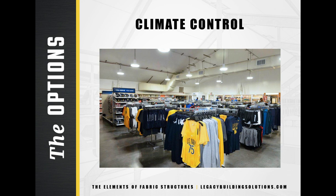Fabric can also make the interior of the building more comfortable, as fabric has thermally non-conductive properties. Unlike steel, fabric does not magnify the outside temperatures, maintaining a more consistent interior temperature. Metal cladding will radiate the temperature variation, creating an interior that is colder in the winter and hotter in the summer. Flexible fabric also minimizes air leakage, resulting in a building which is much more efficient to heat or cool.